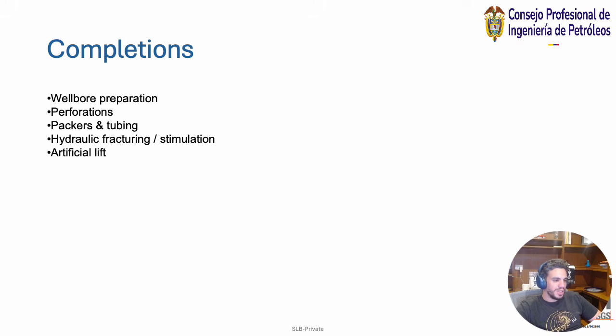So we're going to talk about each stage as they come, but we're going to talk about the wellbore preparation, the perforations, and also perforations like the drilling people do perforations, wireline do perforations, and completion engineers do perforations. So essentially perforation is putting a hole inside your well to achieve something. Then there's packers, tubing, the hydraulic fracturing, and stimulation and artificial lift. And these are different aspects.